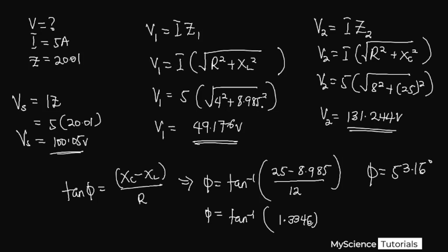We look at the various impedances that we have. If we have a resistor common to them, we add them as we add resistors in series and then write our total. Redraw the new circuit and write the total resistance. If we have inductance that is common, we add all the inductances and then have our total inductance. If a capacitor is present, 1 over C total is equal to 1 over C1 plus 1 over C2, till the number of capacitors you have.